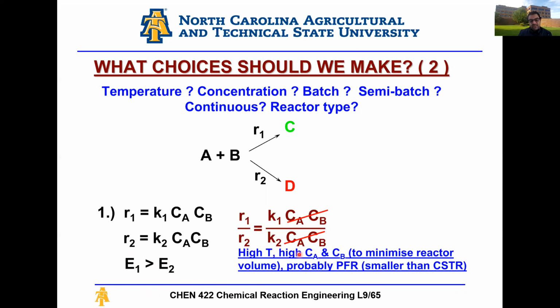On the second test, since there is no dependence on the concentration, I allowed you to pick any type of system, I said it's okay. However, in reality, you want to take the volume of the reactor in mind. So you want to keep the concentrations high to keep your reactor volume low.